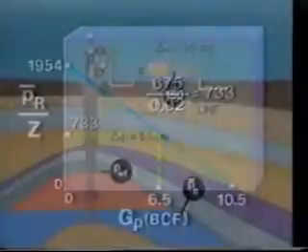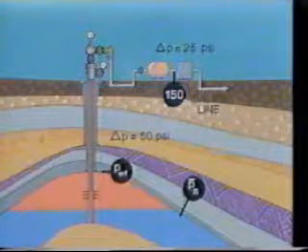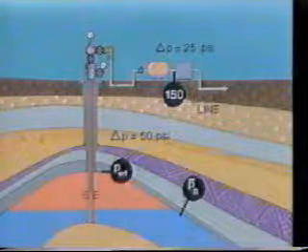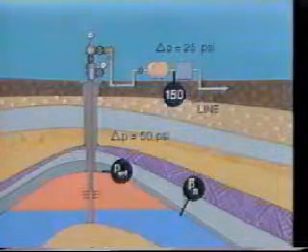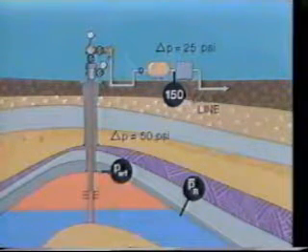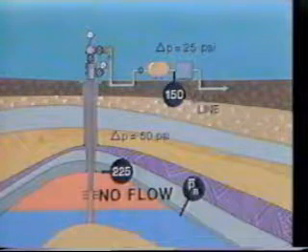If we were to install a compressor at the point of sale with a 4-to-1 compression ratio, the minimum suction pressure would be 150 psi. If to this suction pressure we add the gathering system pressure loss and the tubing pressure loss, we would obtain a no-flow wellbore pressure of 225 psi.